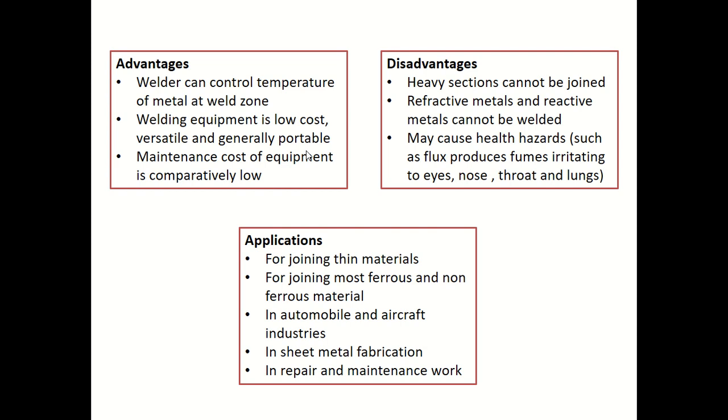Disadvantages include that you cannot use it for heavy sections, and refractory metals and reactive metals cannot be welded using this technique because we are using gases to generate the flame, so it's not recommended. It may cause health hazards. What does it mean? It means the flux produces fumes which are irritating to human eyes, nose, throat, and lungs. So the health hazard aspect is a little bit not good for oxyacetylene welding.